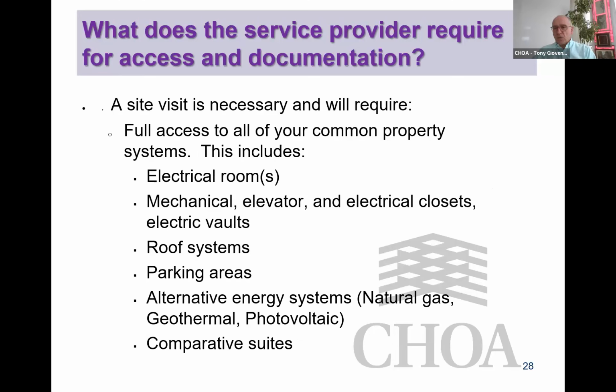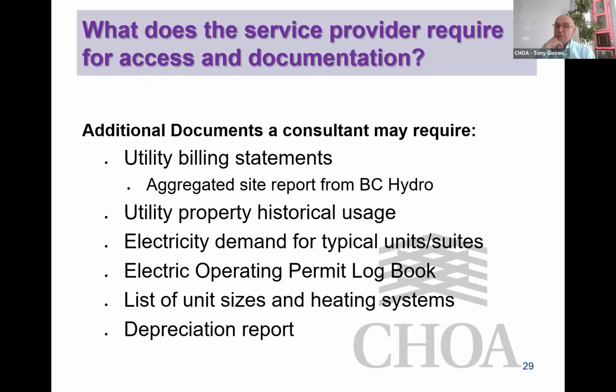This is just a list of all the different types of systems that the site visit is going to basically disclose and require, and I think they're really important. One of the things about the PV systems on the rooftops, and we have some done in the province, and they've been a great success, is that they have to be coordinated with roof replacements. If you're going to put in a new roof, it's a great time to be looking at putting in some PV systems. You don't want to do it prematurely before a roof is replaced. It's a great time to integrate that into new systems.